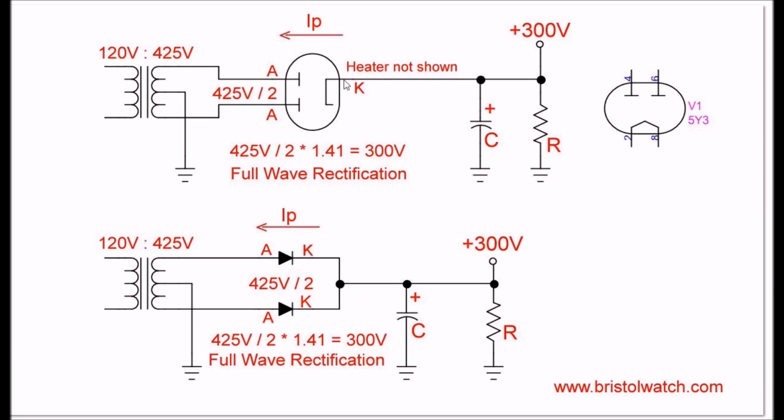Okay, if you're blowing your mind right now, think of what happens here at the capacitor. I am not pushing positive charges onto the positive plate of the capacitor. Instead, what I'm doing is removing electrons from the positive plate, and through the ground setup, I'm adding electrons to the negative side of the electrolytic capacitor.